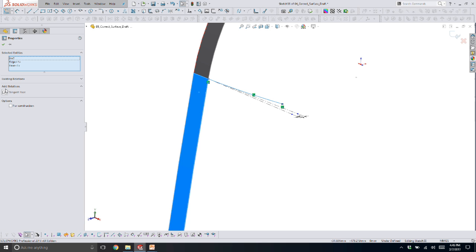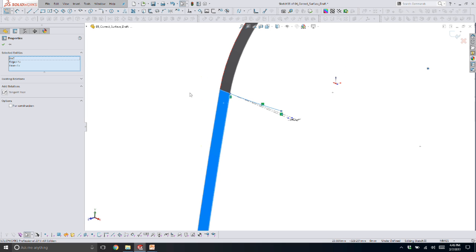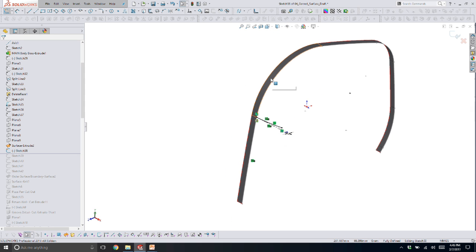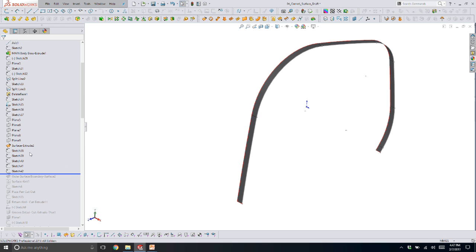So I can make sketch geometry tangent to surfaces or solids, and if you need to make a sketch entity tangent to a face, you can do that. I add the tangent face to this. Now, whenever I update this surface, maybe it goes to 4 degrees, the arc updates because of that tangent face relation. So these are the additional curves required to make this shape.